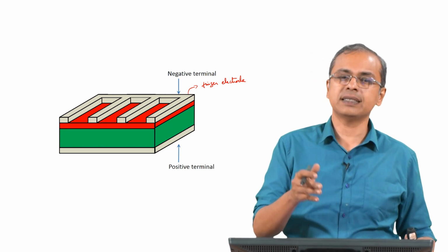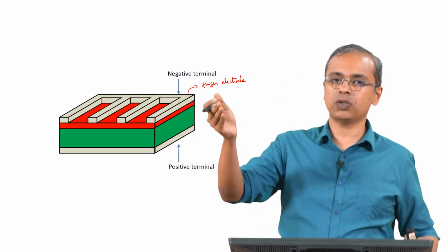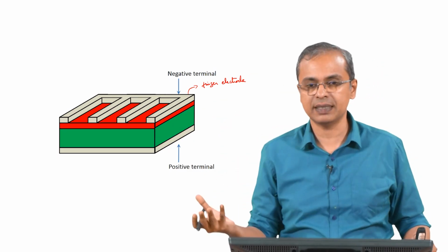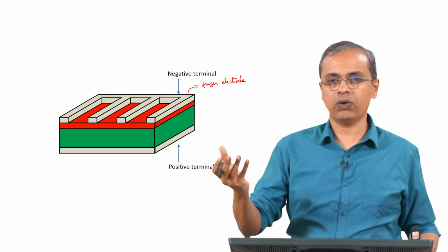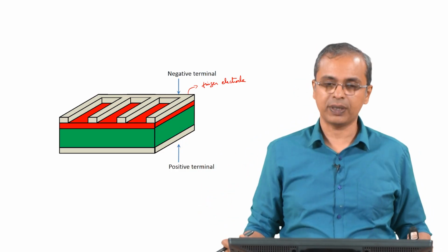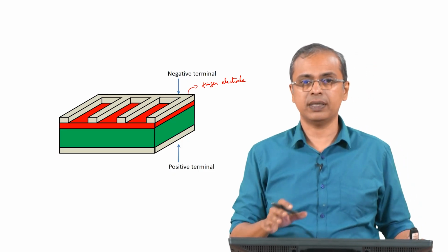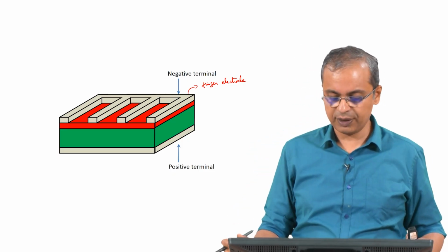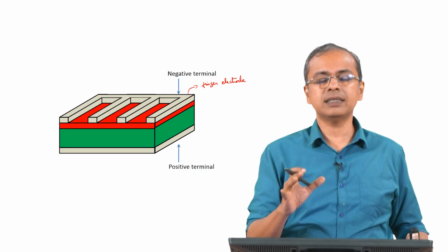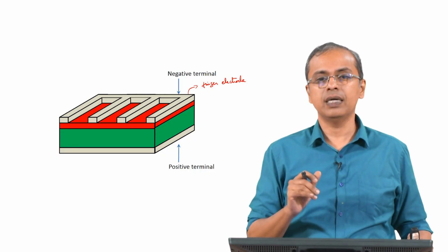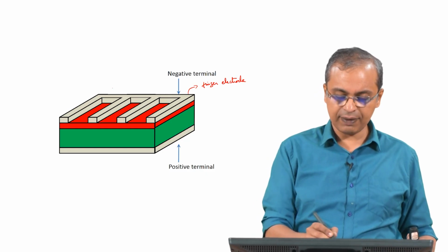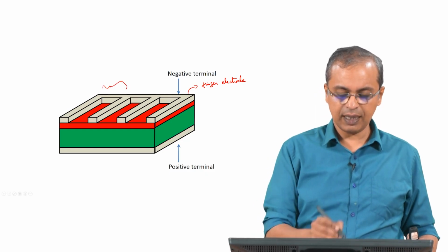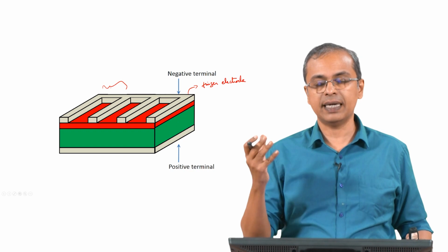So because of practical considerations like this, you do not even reach the Shockley-Queisser limit. Even though the Shockley-Queisser limit says 30 odd percent you will get, what you practically get is more like 20 odd percent, 24%, something like that. This is one of the contributing factors to it. It is not the only factor, but it is one of them. But essentially you have to put this finger electrode, which basically means that some areas are masked, but you have plenty of area at various locations where it is open to sunlight, where the sunlight can come through.